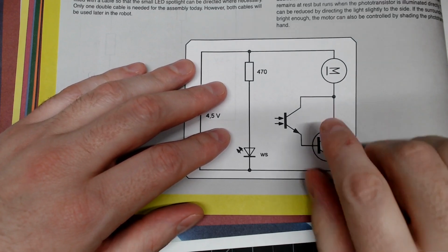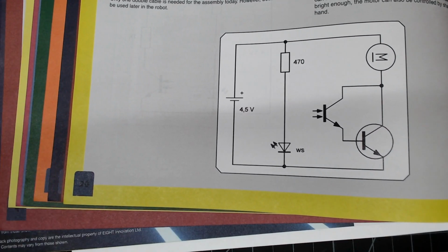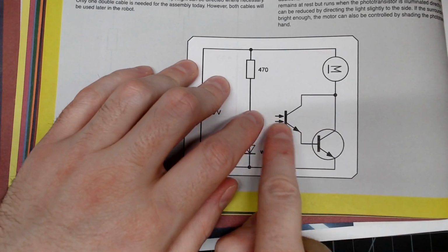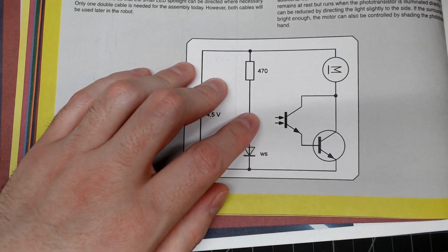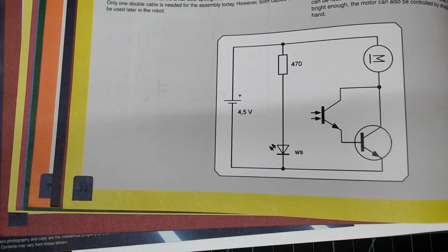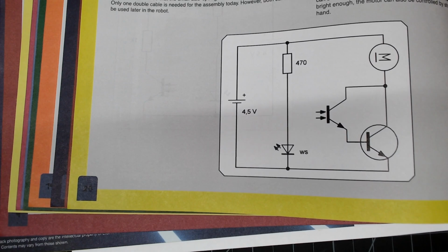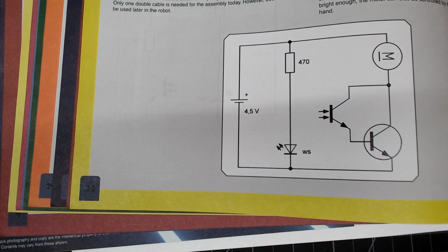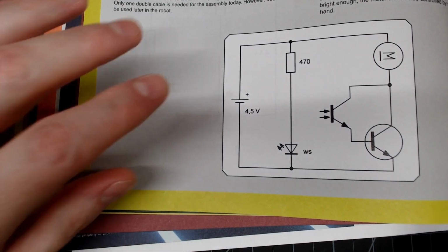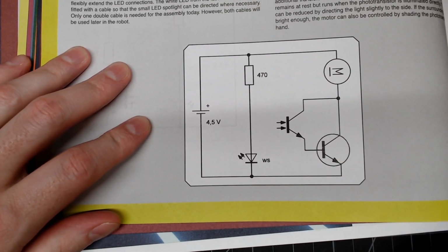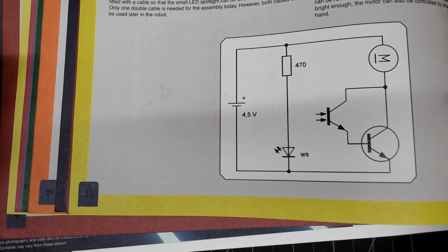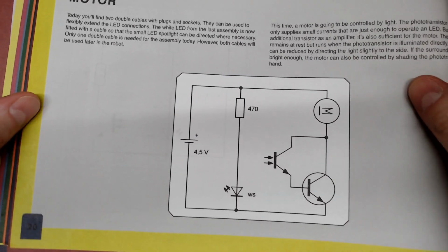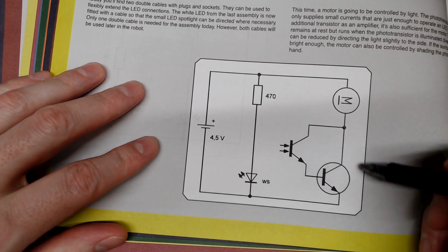We can get a bit, but we can't source it. So we're doing amplification. All we're doing with this small amount of current is driving this transistor. That's the only thing. Its entire purpose is to drive the transistor. And as we saw before, we only need a few milliamps to do that. And that allows us to have a considerable amount of current flow through here, in our case, 100 milliamps or so. So that's why we have to have this separate transistor.